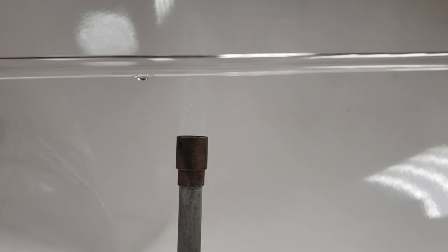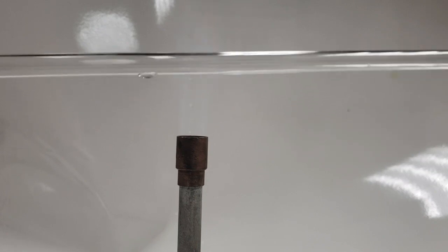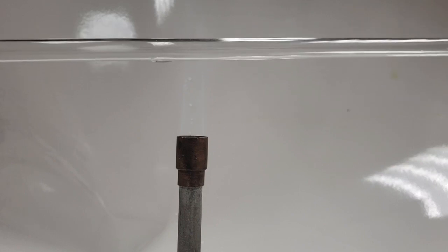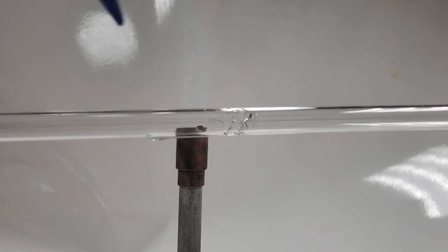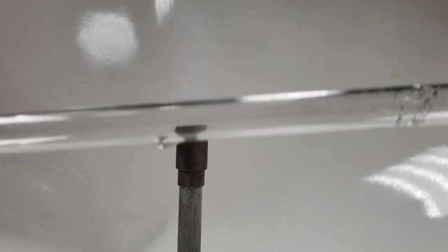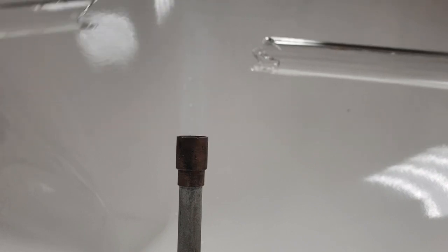What we're trying to do is thermally stress the glass. Now, if this was being used for really important stuff, we wouldn't want to do it this way. But for what we're doing right now, it works well. And there you can see that nice crack form, right? So if I come in here with my hands, you can see I should be able to just easily break the glass off. Now, that's a very rough edge, right?